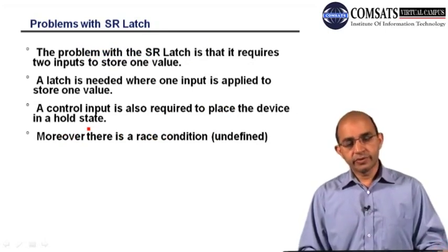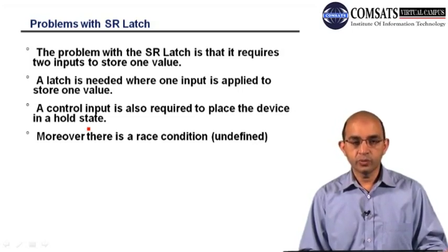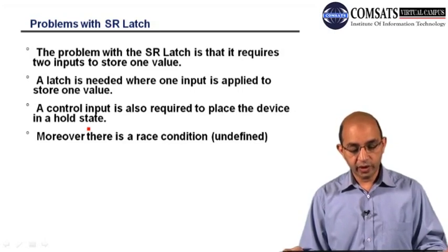So there are some problems with this SR latch. The first problem is that we need two inputs, S and R, in order to store a single bit only. The second problem is that a control input is also required to place the device in a hold state.